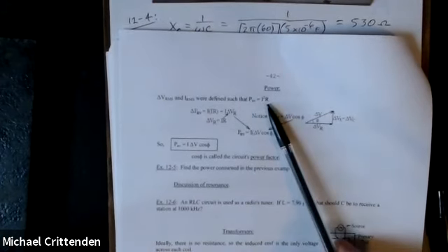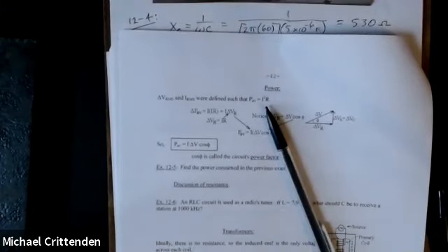Only the resistor actually consumes, well, ideally anyhow, under textbook conditions, only the resistor consumes energy. The resistor takes energy away from the flowing electrons, converts it into heat. The heat soaks away into the environment. Reactance does not dissipate energy like that. It very briefly stores energy in either electric or magnetic field, depending on whether you're talking about the capacitor or the inductor, and then it comes back into the circuit.